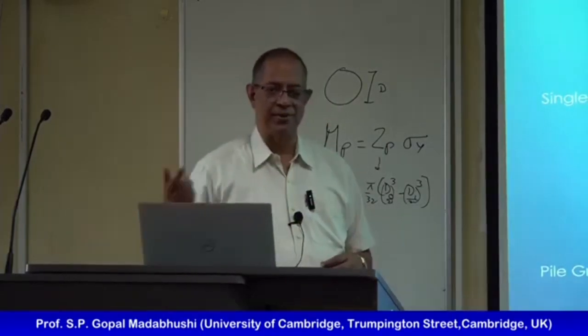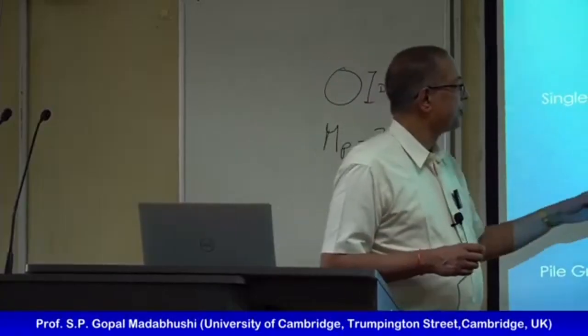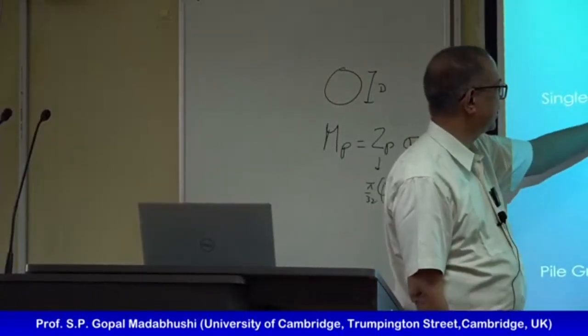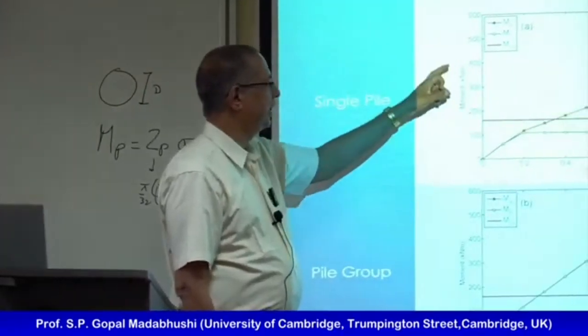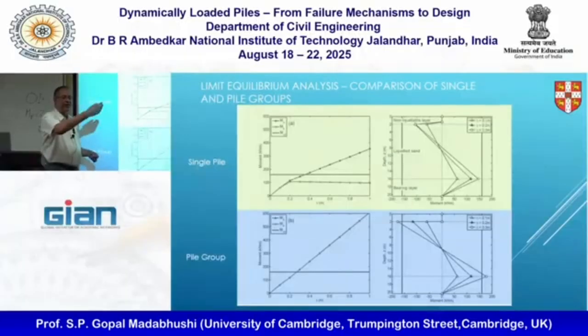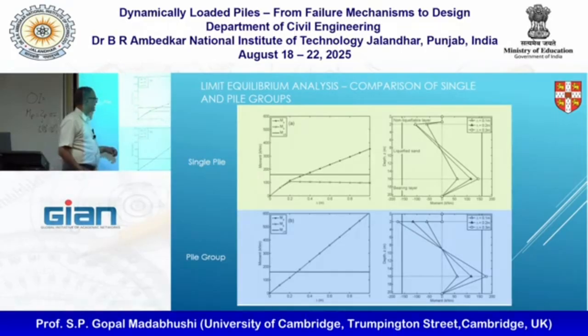Anyhow, so radius of gyration also comes into it. Okay, so that we know, and for this it was calculated at about 180 kilonewton meters for the experimental pile. And then obviously we had an aluminum pile, calculated the ZP for that, and the yield stress, and then converted that into prototype scale using the scaling laws we learned yesterday. So that is the limit.